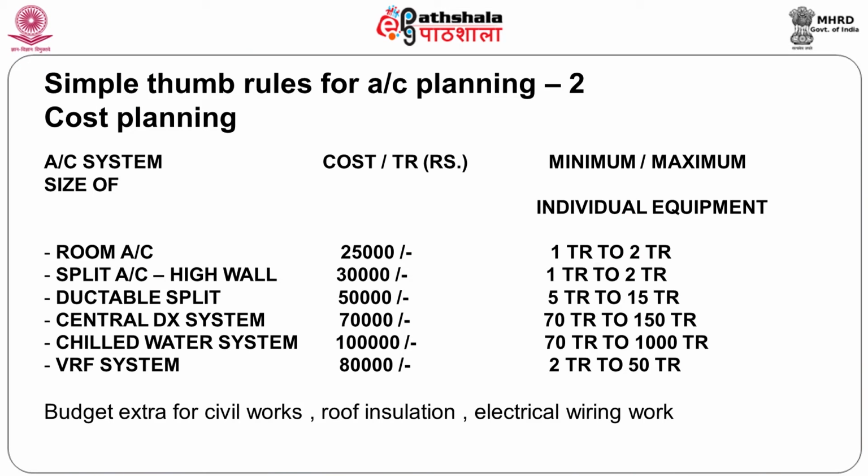Now, if you know the capacities, obviously the next thing will be not too important, but these are the kind of figures that you would look at in terms of budgeting, in terms of mentally evaluating whether I should have air conditioning or not, whether it is cheaper to put in a 9-inch brick wall and save on tonnage, or whether it is easier to put in insulation on the roof. Awareness of this figure helps you to trade off between insulation that you should put on the fabric to improve upon the K value that you would get.